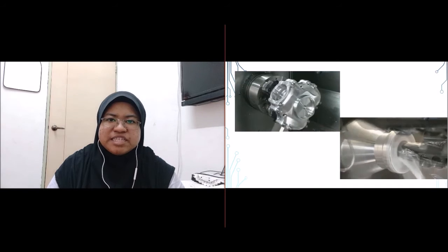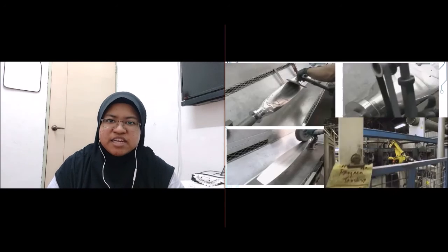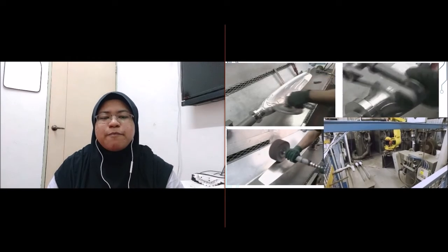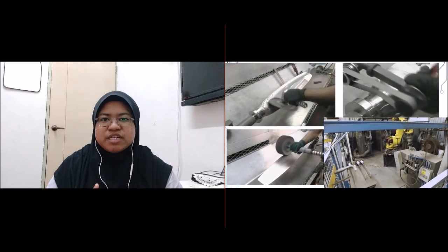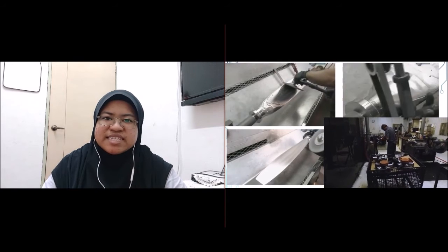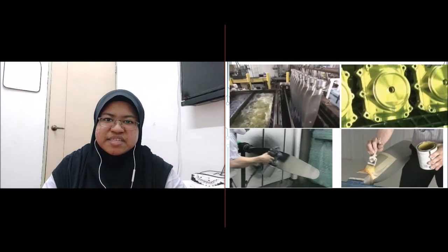For the propeller blade finishing, a rotary sander and brake sander will remove any marks that the machining process left behind. Then the blade is buffed by using the polishing wheel. The finishing step is usually done automatically first, then will be done manually by a highly experienced worker. After that, the blades are dipped into a strong detergent. The acidic solution will remove any dirt and grease on the blade.